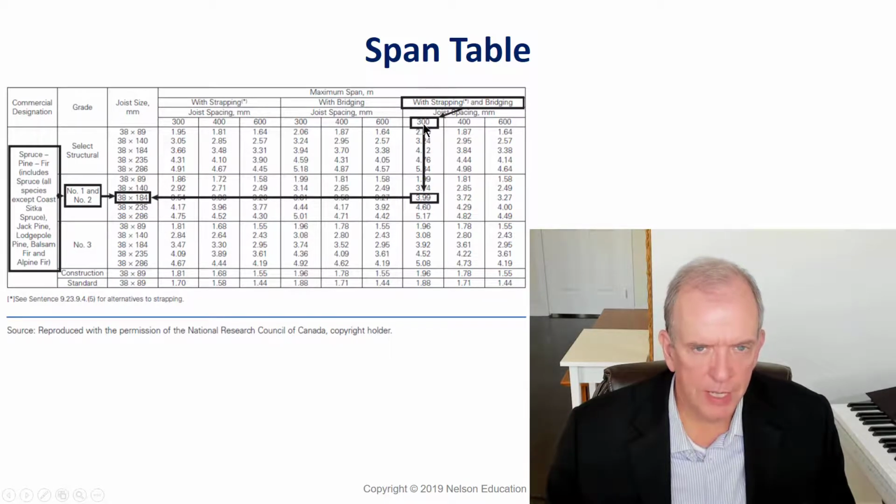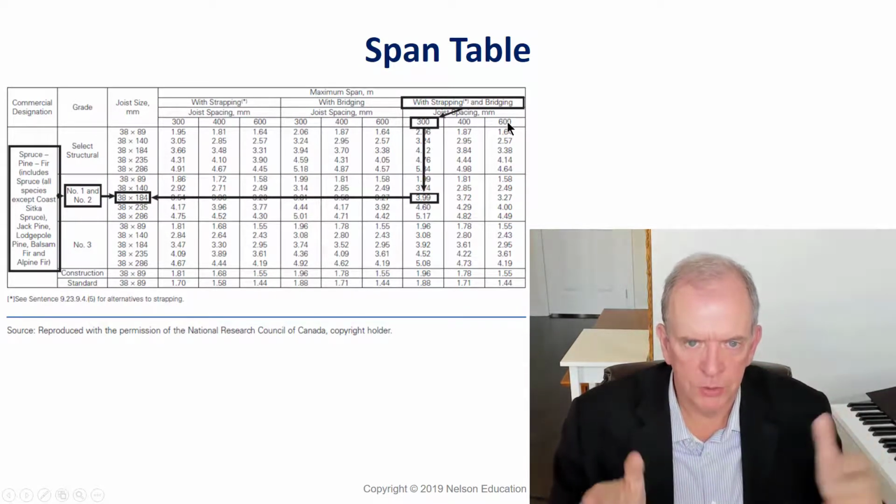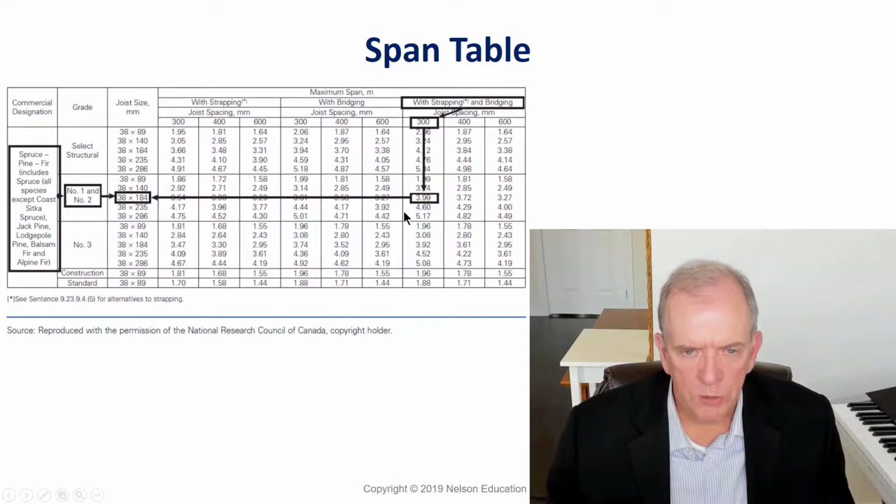This is the spacing. So that's 12 inches, 16 inches, 2 feet, or 300 millimeters, 400 millimeters, 600. That's the spacing you're going to put the joists at. So if I had 3.8, I can't go with 16 inches because it won't span enough. This has to be more than whatever I want to span. If I've got a 3.8 meter span, this will work.